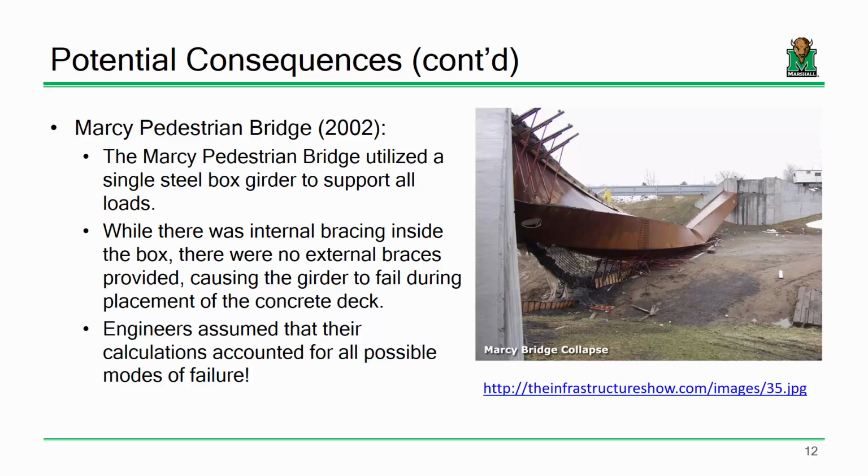And then there are things called live loads, where it's people walking around, or in the case of vehicles going over a bridge, that's a load that's moving around, and there can be wind loads in addition to that, and other types of impact, like the vehicle not only is moving, but also maybe it's coming over a speed bump. And so more than just the vehicle weight will be applied to a roadway surface in the case of speed bumps. And so in this case, people just weren't thinking of all the possible forces that could be applied to a structure, and it resulted in a pretty spectacular failure.